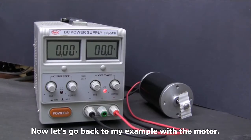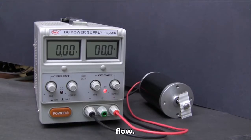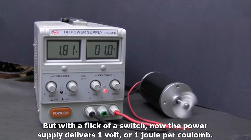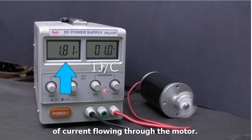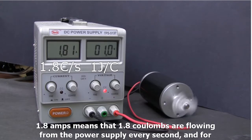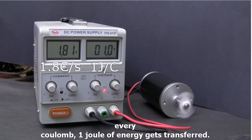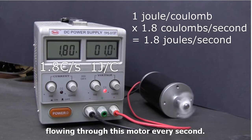Now let's go back to my example with the motor. With the power supply set to 0 volts, no current can flow. But with the flick of a switch, now the power supply delivers 1 volt, or 1 joule per coulomb. And over here, the power supply is measuring the amount of current flowing through the motor. It's roughly 1.8 amps. 1.8 amps means that 1.8 coulombs are flowing from the power supply every second, and for every coulomb, 1 joule of energy gets transferred. So 1 volt times 1.8 amps means that 1.8 joules of energy are flowing through this motor every second.